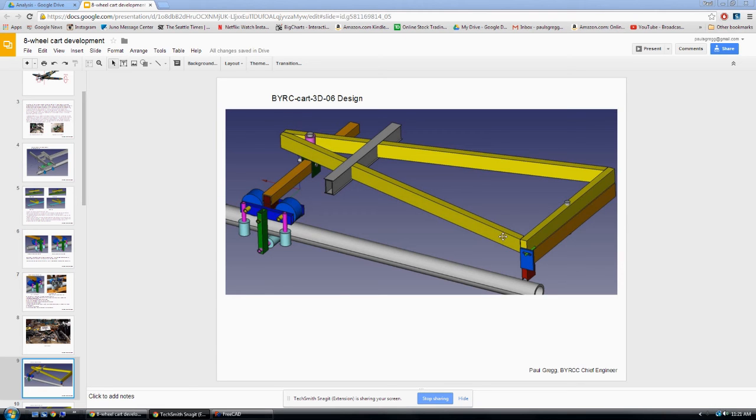These long members that are the frame, it's pretty far. It's 34 inches between here, and if you want to keep your frame light, this rectangular bar here, you need to put it standing upright, because that's where the moment of inertia is higher.